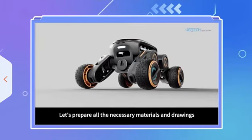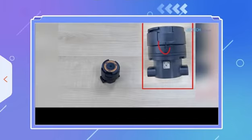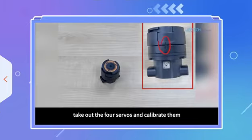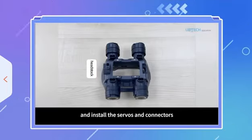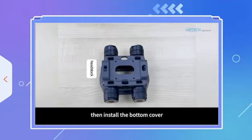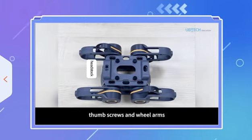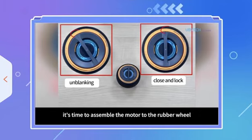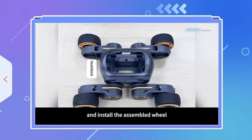Let's prepare all the necessary materials and drawings. First, take out the 4 servos and calibrate them. Take out the expansion box and install the servos and connectors. Then, install the bottom cover, thumb screws, and wheel arms. Now, it's time to assemble the motor to the rubber wheel and install the assembled wheel.